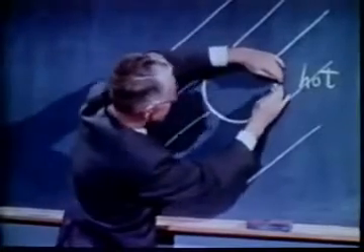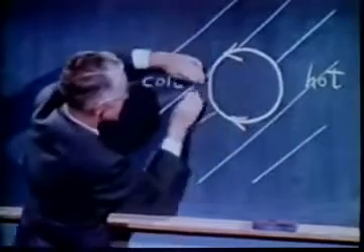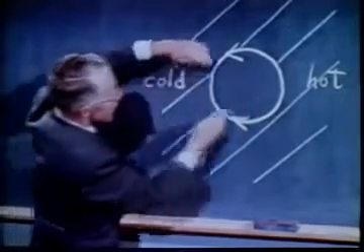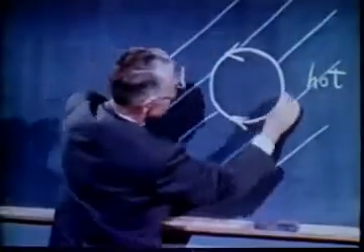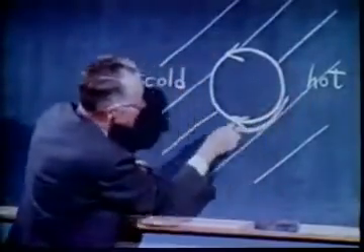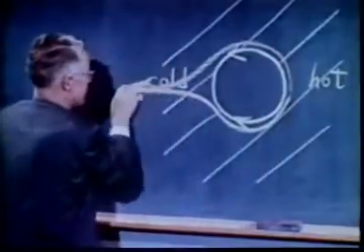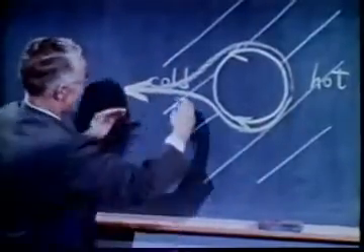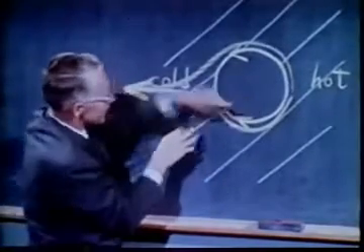This movement of surface with its viscous drag upon the boundary fluid will pick up a sheath of liquid and jet it off the back end. By jetting liquid this way, the bubble propels itself that way. It will swim up the temperature gradient, always moving to the hot region. Here we have a bubble. It moves to any hot region.